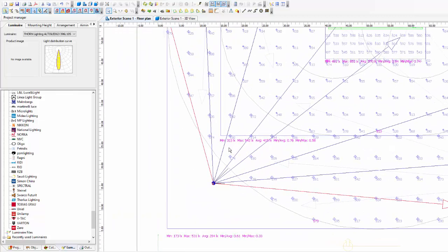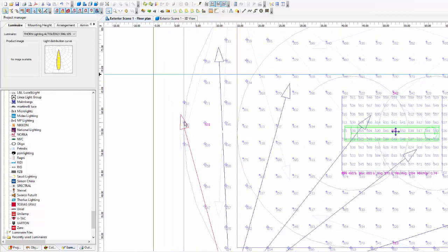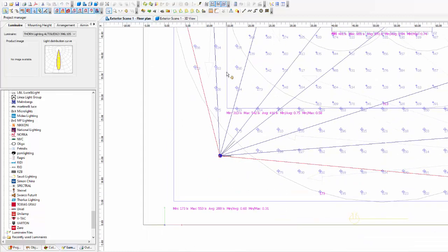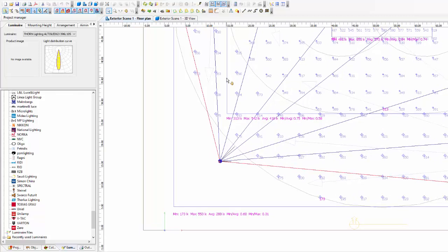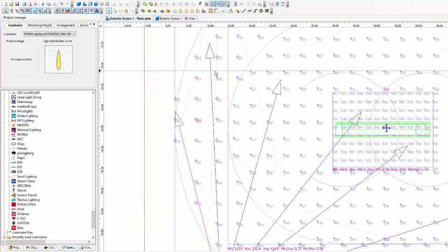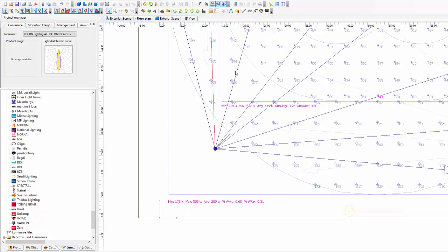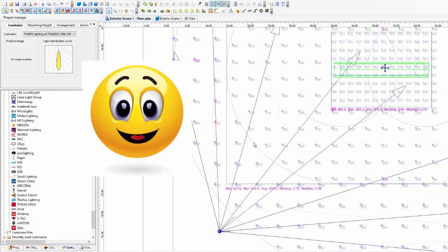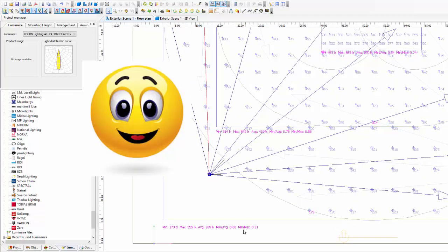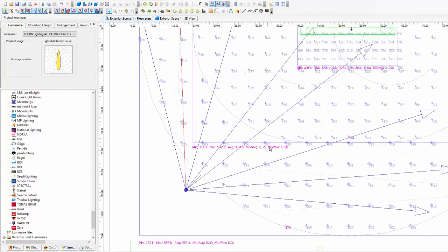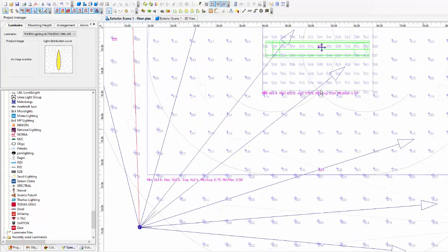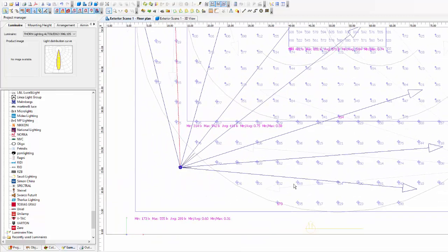So I'll need to work for 16 lux more. Okay, so I will adjust it here. 288. Okay, now I need a little more. What if I adjust it there? 289. Closer. My lux value is still okay because it's 0.6, and my infield is still okay, and my pitch is always perfect. So let's go and try this one.